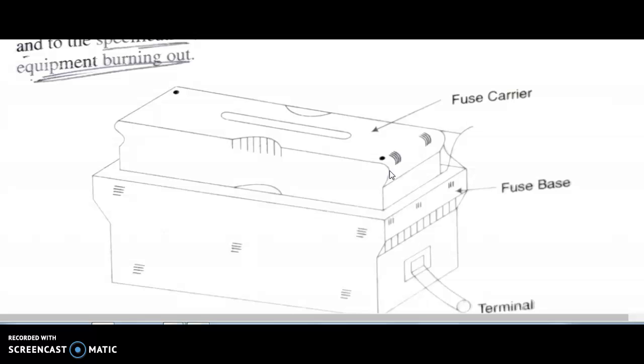Because of its simplicity and low cost, this type of fuse is extensively used as a protective device on low voltage circuits. But the fuse wire is exposed to the atmosphere, therefore it is affected by the ambient temperature. As the fuse is affected by ambient conditions, its time current characteristic is not uniform and gets destroyed with time, resulting in unreliable operation and lack of discrimination.